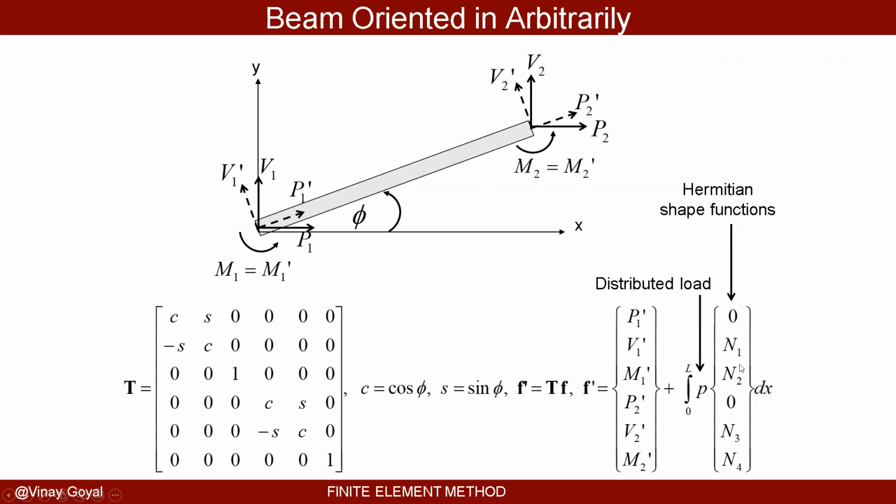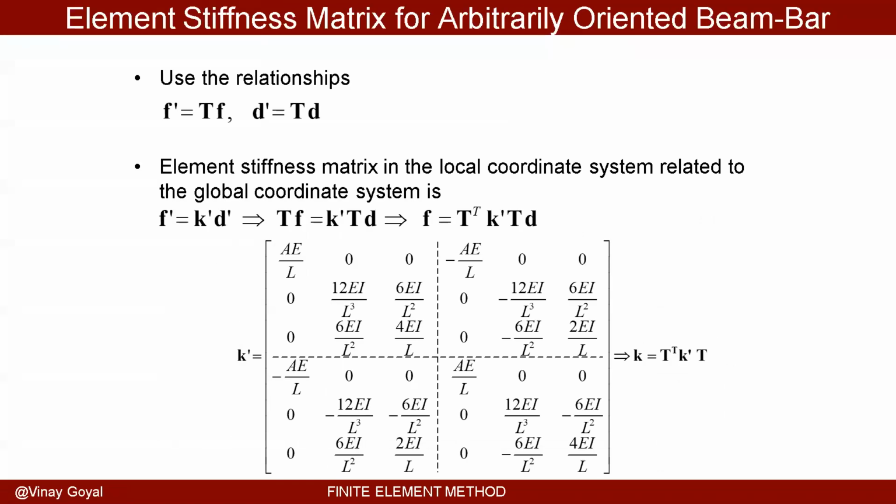Then finally, I have the distributed forces that are shown here. And these are the Hermitian shape functions. Notice how the transverse loads to this beam do not affect the axial component, because the transverse loads only affect the transverse components, not the axial components. And so that's why you see a 0 here and a 0, 0, a 0 here, because that corresponds to U1 and U2, the axial deflections, while these shape functions really are for the transverse loading condition.